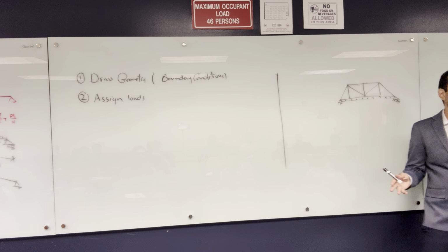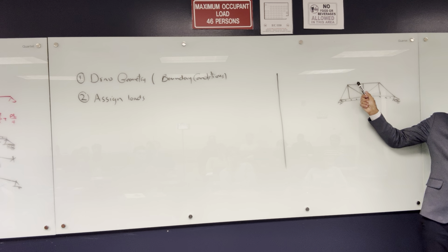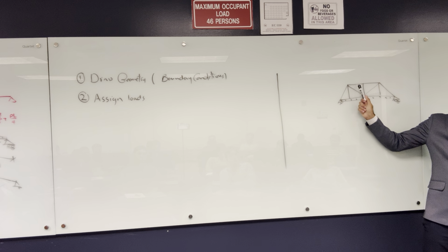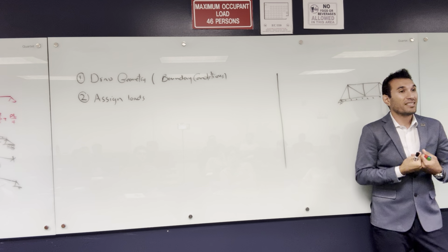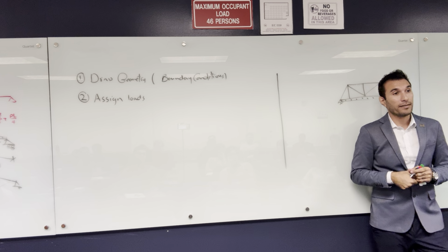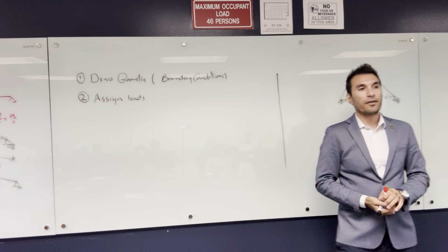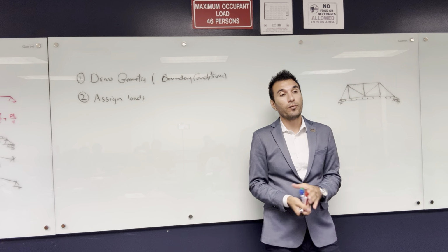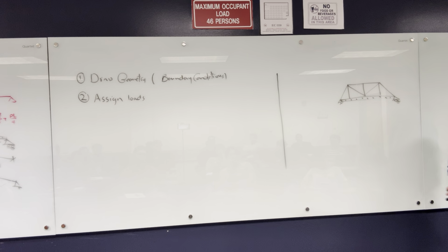So if you want to be accurate, yeah, you have to consider the own weight of the truss element, and try to see if this truss element is going to fail under this moment or not. Like with this section, if you bend it with its own weight, is it going to fail or is it going to pass? All right. But in all engineering problems, there's always own weight. Any member, like wood, has its own weight. So anyway, that's about the geometry.